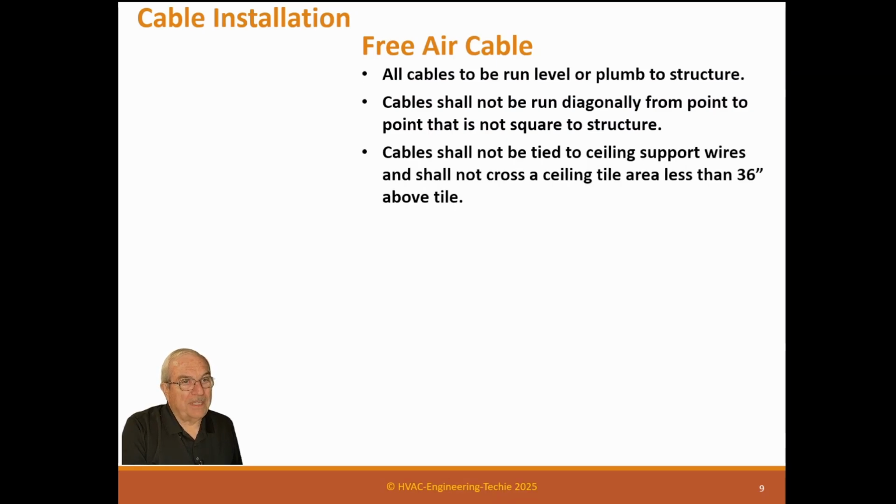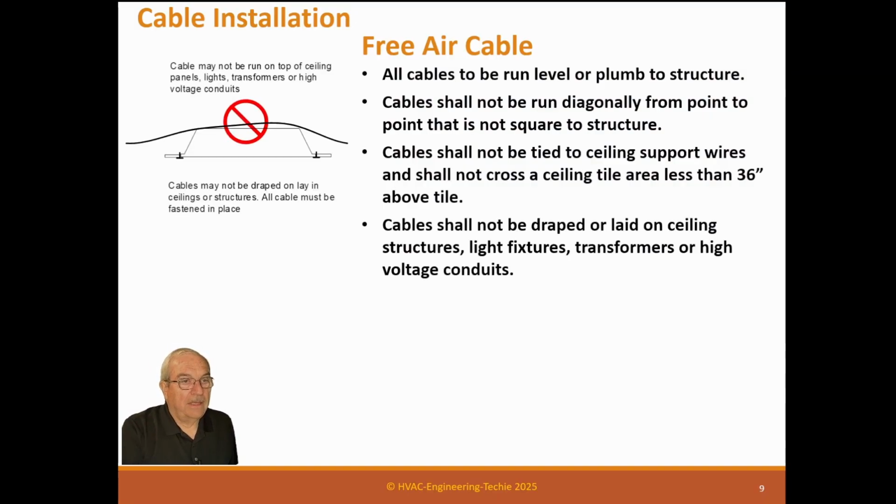Cable shall not be tied to ceiling support wires and shall not cross the ceiling tile area less than 36 inches above the tile. So if you run a cable low through the middle of a tile and someone has to access that, they're going to move your cable. And if it isn't long enough, it will get damaged. So you can't do that. You've got to stay above the tile. Cable shall not be draped or laid on ceiling structures, light fixtures, transformers, or high voltage conduits, because you can pick up radio frequency, and that can be a problem for your communication.